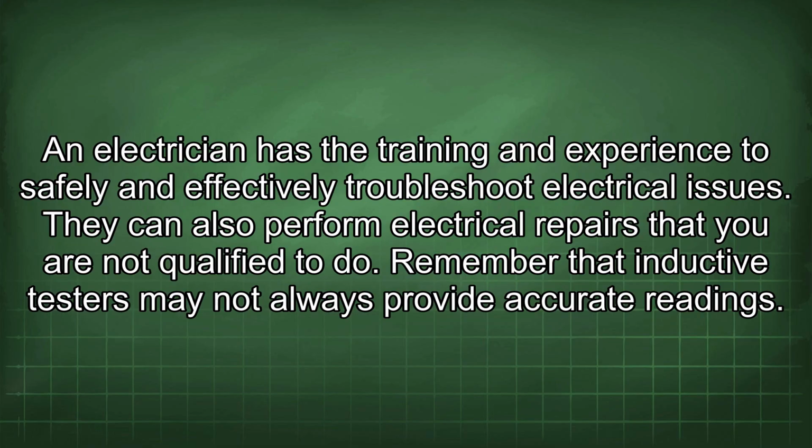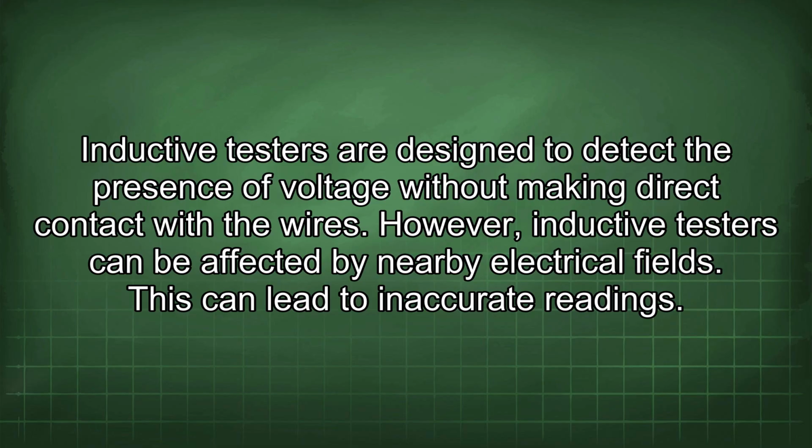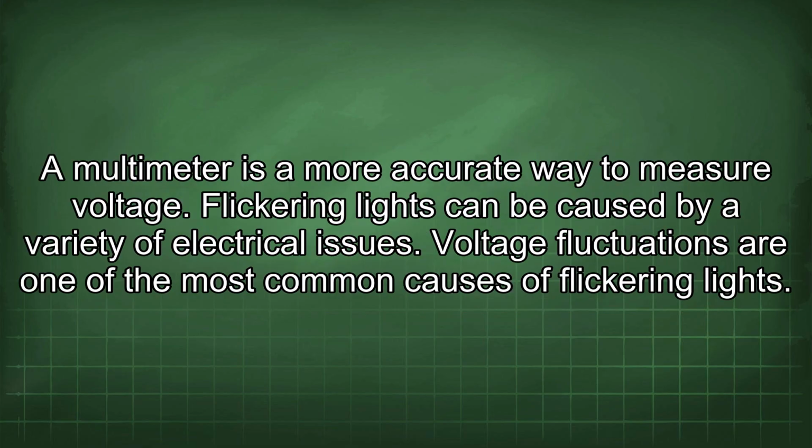Remember that inductive testers may not always provide accurate readings. Inductive testers are designed to detect the presence of voltage without making direct contact with the wires. However, inductive testers can be affected by nearby electrical fields. This can lead to inaccurate readings. A multimeter is a more accurate way to measure voltage.